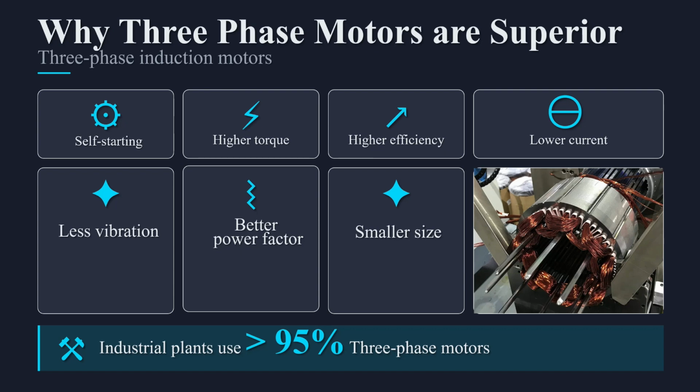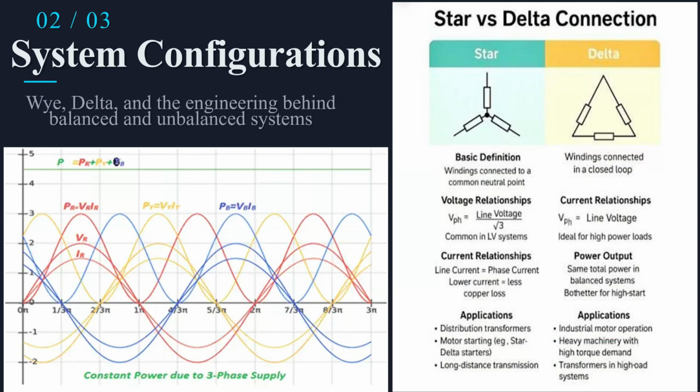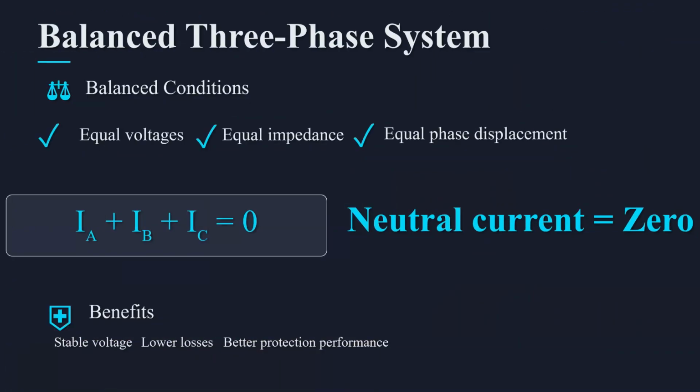For a sinusoidal waveform, the relationship between peak and RMS voltage is Vrms equals V peak divided by square root 2, resulting in approximately 230 volts RMS from a 325 volt peak waveform. This explains why household electrical equipment is rated according to RMS voltage rather than instantaneous peak values.